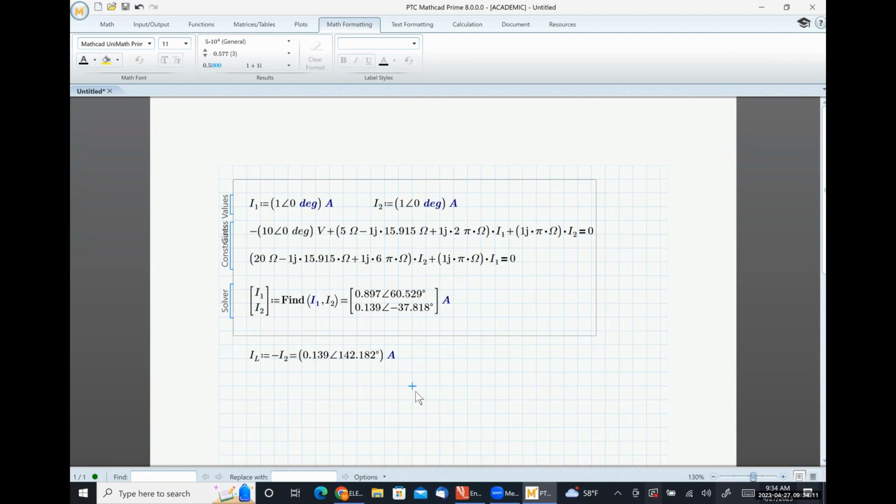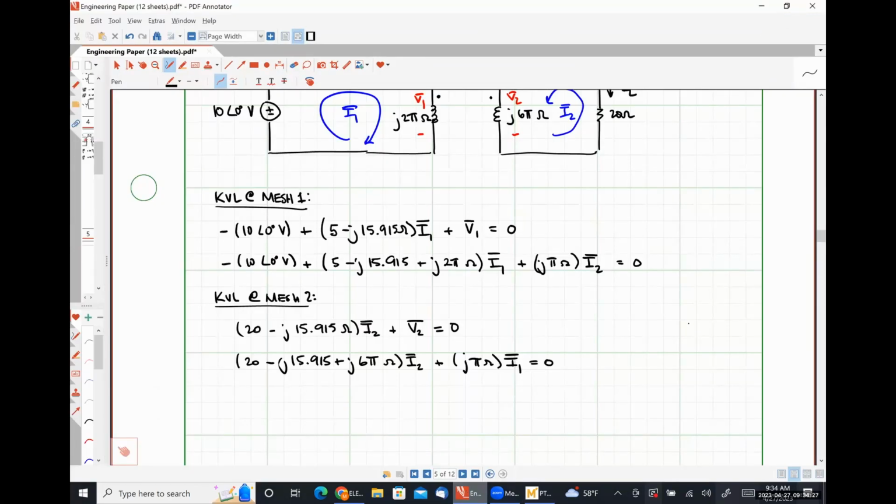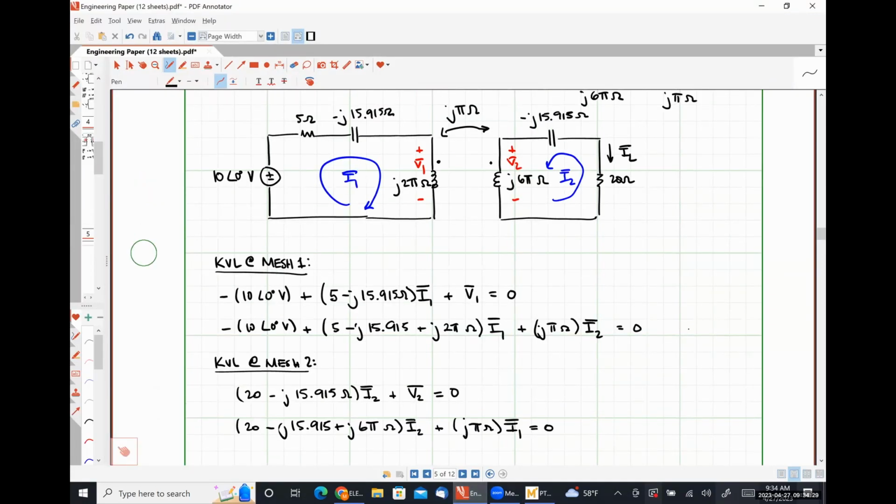So it's not hugely different than what we did for that first section of class where we were simply analyzing circuits in the frequency domain. The hiccup here comes from the fact that we have to remember to include the mutual terms, and we have to make sure that we get the signs right on both the self-induced part and the mutually induced part of both voltages, or everything's going to go wrong, right?